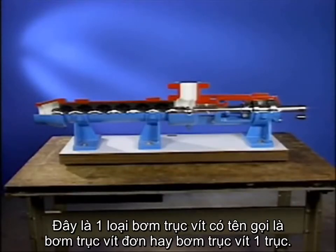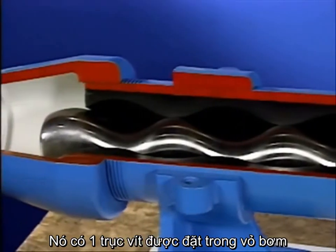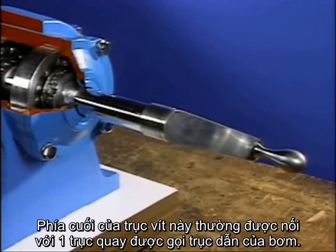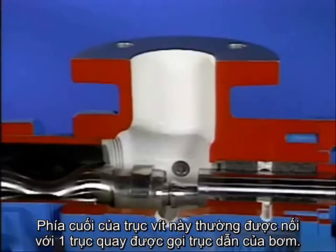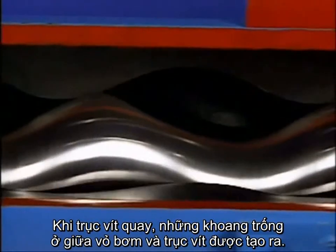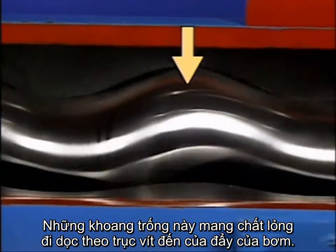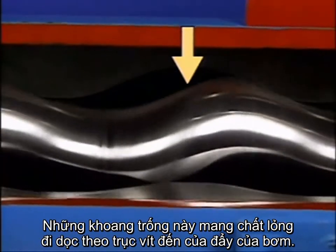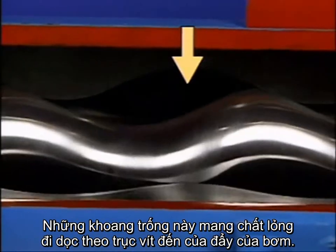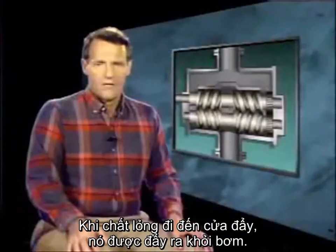This is one type of screw pump called a single screw or progressive cavity pump. It contains a single screw that's located inside a casing. This end of the screw is normally connected to a driver. As the pump operates, processed liquid is drawn into the pump through the suction port. As the screw rotates, cavities form between the casing and the screw. These cavities move or progress toward the discharge of the pump, carrying the processed liquid along. When the liquid reaches the discharge, it's forced out of the pump.